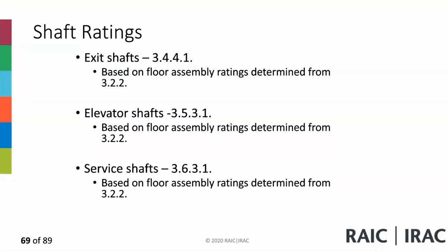Exit shafts and elevator shafts are easy. They're going to take the rating of the floor. So if you have a 2-hour floor, you have a 2-hour exit shaft. Same thing with elevator shafts. Service shafts are a little bit different. So to double check it, let's take a look at 3441.